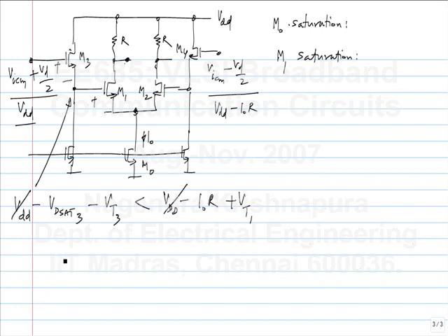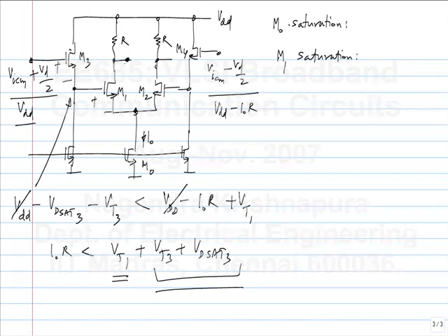So what does it mean? This was the original constraint, and this much has been added to it. So you have a lot more freedom now. In fact, in somewhat higher voltage versions, this is the way the circuit is used. The source follower also works as a buffer and helps to some extent. So the basic constraints can be evaluated. If the levels are not convenient, you do level shifting. But the idea is you have a logic family, so the input level should be compatible with the output levels, so that you can connect one logic gate to another. Otherwise, you can't use the logic family.